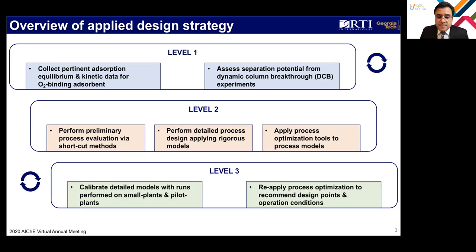And finally, when available, as is the case for this project, we can go ahead and construct a pilot plant. We can pack some adsorbers, some columns with oxygen binding adsorbents, and then calibrate our detailed models for the cycles. That's one thing that is important to do.